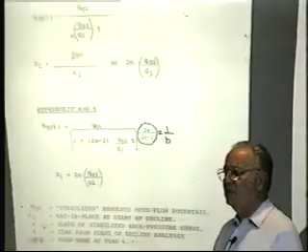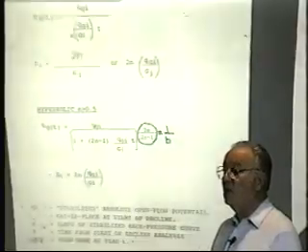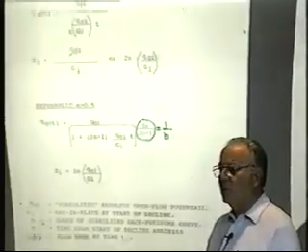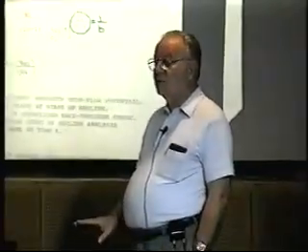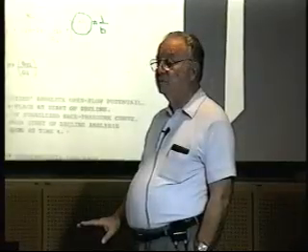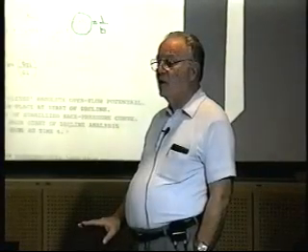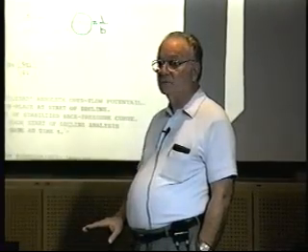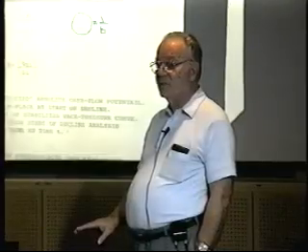When we get to the Guymon-Hugoton, which we matched with a model, the Krider layer pressure was around 100 pounds. The Harrington was 300 pounds. So you're throwing away 200 pounds in your material balance match. And it seems like you're deficient in place, but it's there.